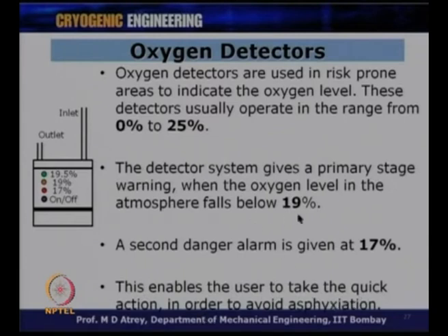So, as soon as he hears the alarm, he should open the doors and windows, and he should stop transferring cryogens and things like that, to ensure that the oxygen levels do not go below a particular limit. You are not getting asphyxiated. It is a very important aspect, and therefore, oxygen alarms should always be there in the lab atmosphere.